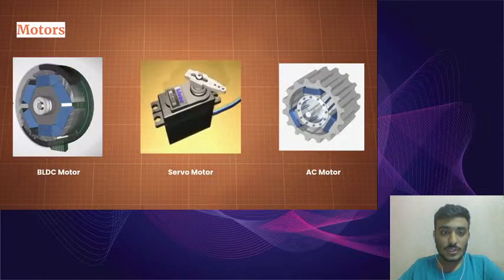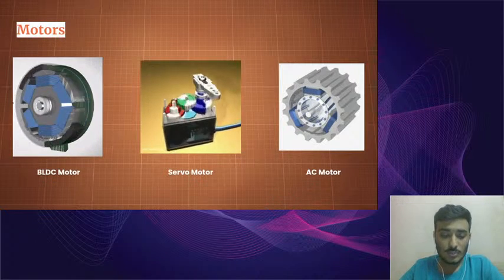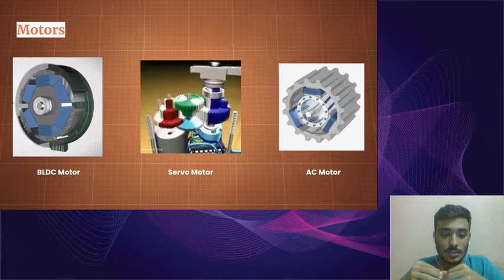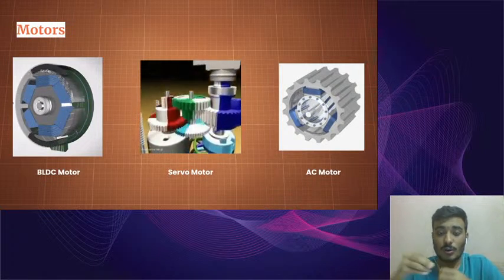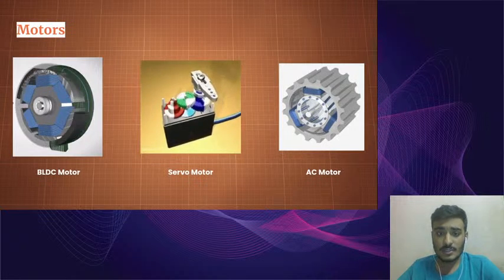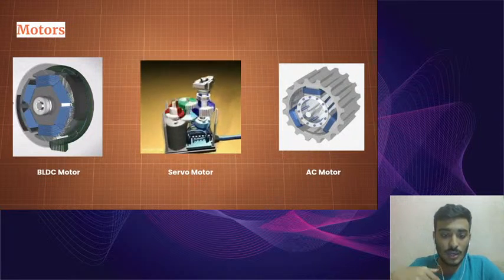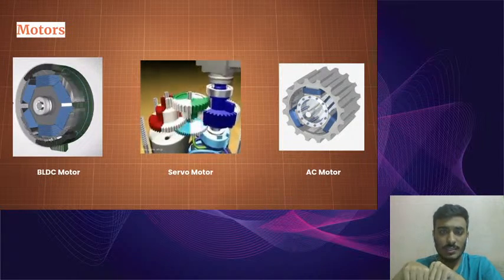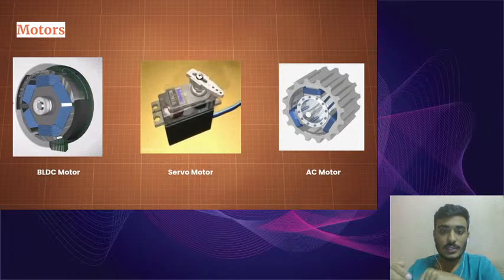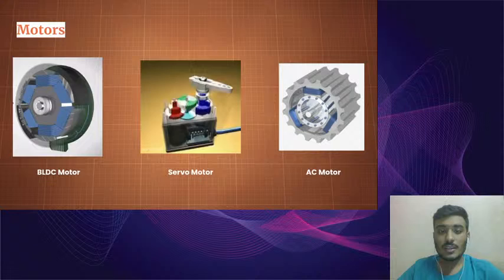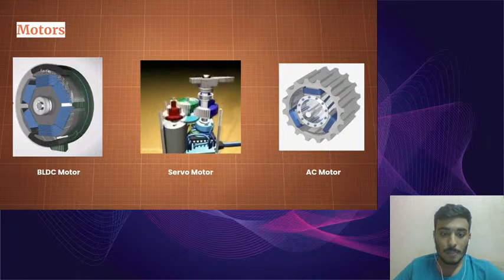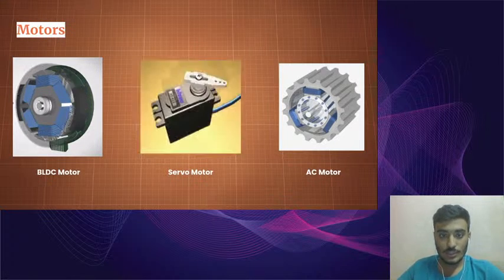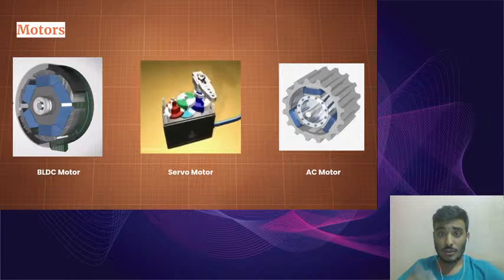And one more point to discuss in the motors, there is something called stepper motors as well. I'm sorry, I don't have the GIF for that here, but stepper motors are something like DC motors which do a particular function in discrete steps. They have multiple coils in them which are organized in what we call phases. Each movement takes a particular phase and then goes on to the next. This is the advantage that stepper motors have over servo motors. In stepper motors, you have greater precision, greater control over the movement, velocity, and acceleration of a particular component of a robot.